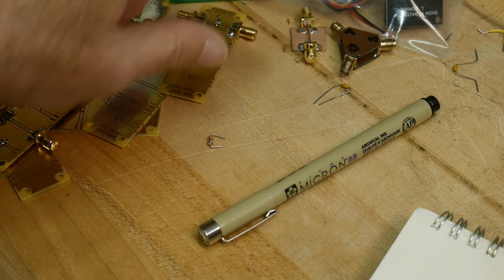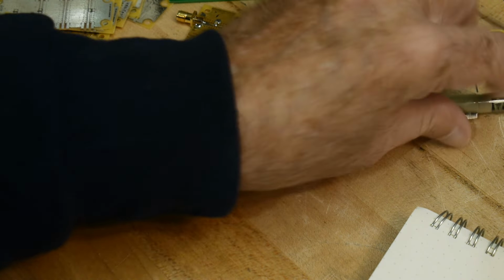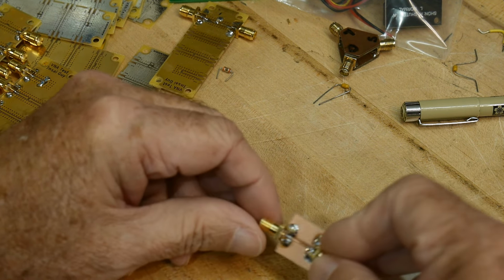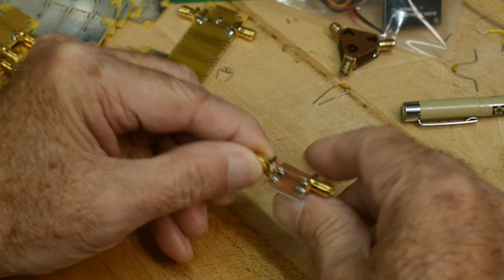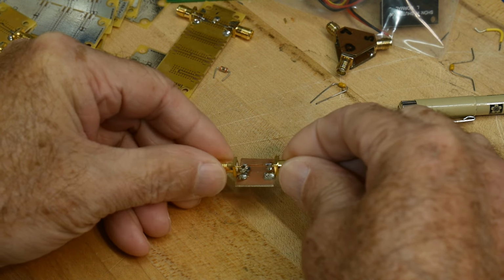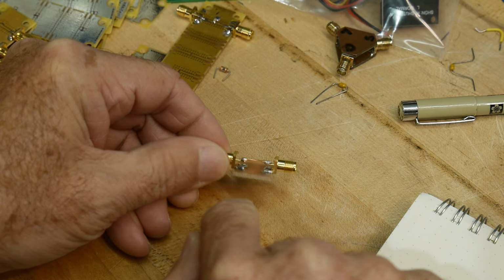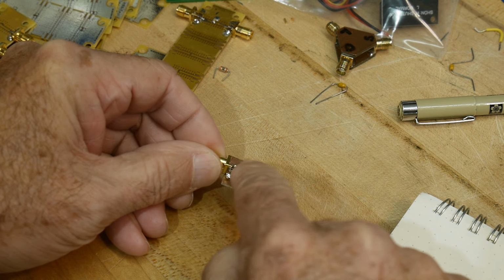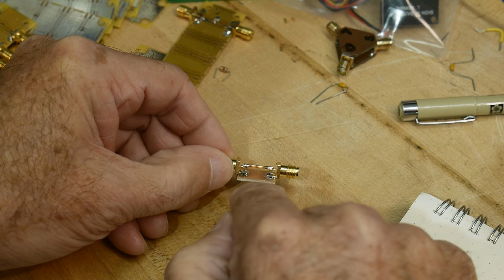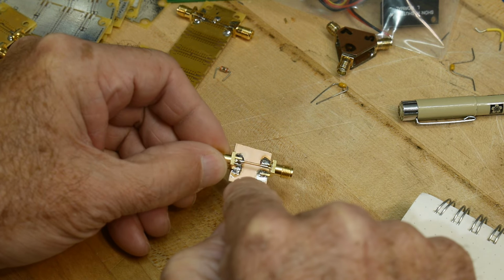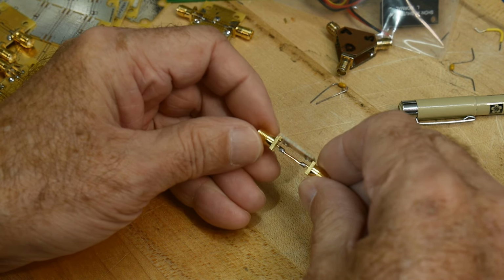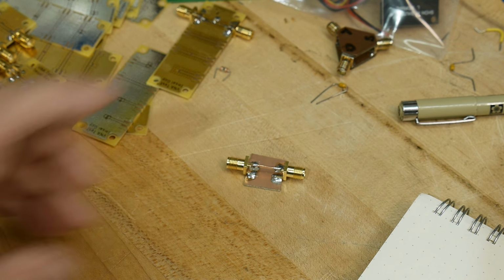Okay, so before we can measure our capacitor, we need to have a fixture. Okay, what's called a fixture. And I have designed and built my own fixture. And it is going to be 2 coax connectors on a ground plane. And there's going to be a wire that goes across. So that's going to be my signal wire, okay? And then if I want to add capacitance, I can put it between my signal line and ground, okay? And so the first thing we need to do is calibrate our system. So let's do that.